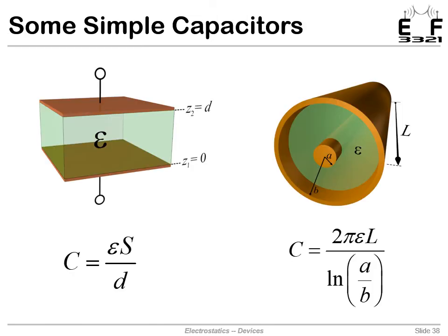Unfortunately, we're not going to exercise that recipe in this lecture. That will come in some following examples. And the two important results from those examples: one, we analyze a parallel plate capacitor. This is a classic analysis. And the capacitance of this parallel plate is the permittivity times the cross-sectional area divided by the plate spacing. We also go on to analyze the capacitance of a coax, where we have a center conductor, we have an outer conductor, some kind of dielectric fill, and that coax is some distance L long. And we arrive at a nice, pretty clean expression for the capacitance of that structure. So here we're exercising Cartesian and then cylindrical coordinates. So that's it for this lecture.